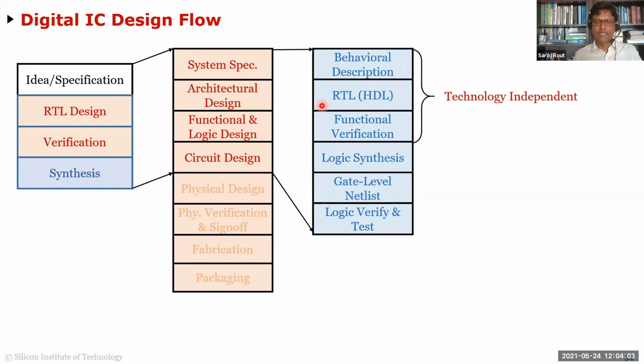So you're not writing any code which cannot be synthesized, like a printf statement. A printf statement is valid SystemVerilog code, but obviously you can't synthesize it. But like the code which I showed you just before in the diagram where it says always at positive edge, that is synthesizable code, right? So it is getting closer to your physical circuit now. So your chances of getting a circuit out of this is now almost 90% or 99%, depending on the complexity of the circuit. So that's your RTL part.